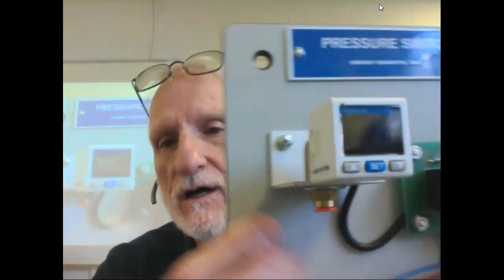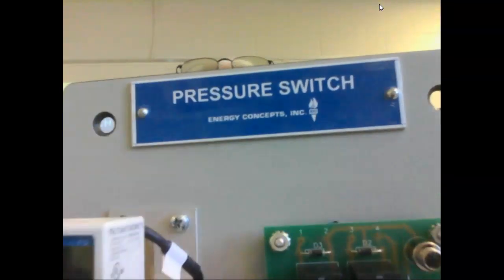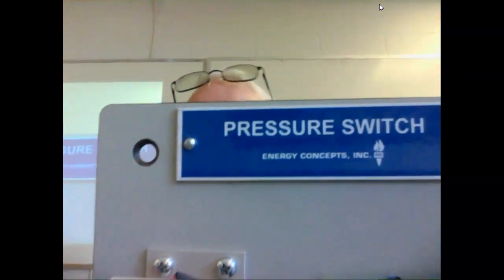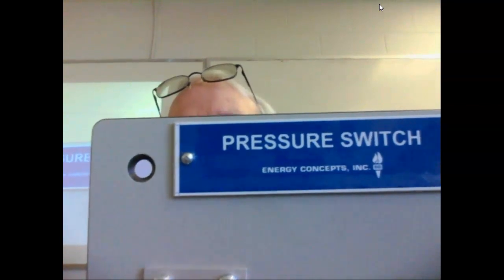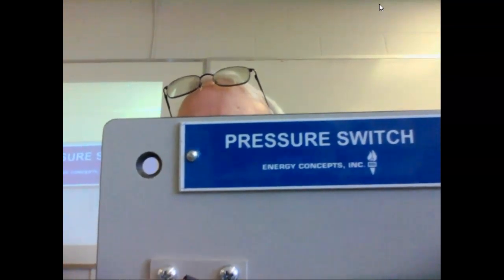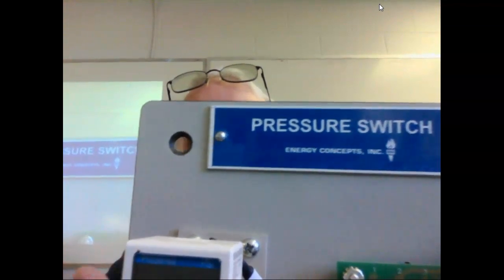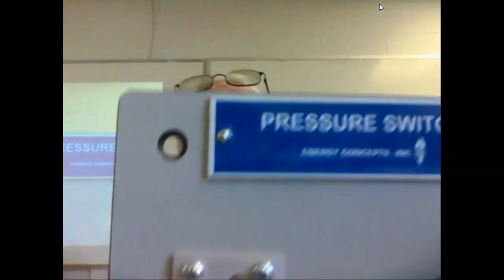And what the sensor does is it brings in these control relays. And in the control relay, we put 120 volts across the contacts. Does that make sense? So what's nice about a relay is what controls the coil does not have to be what is being switched. Y'all understand that? So what we're doing is the sensor, we power it up all with 24 volts, but it's switching a 120 volt circuit.